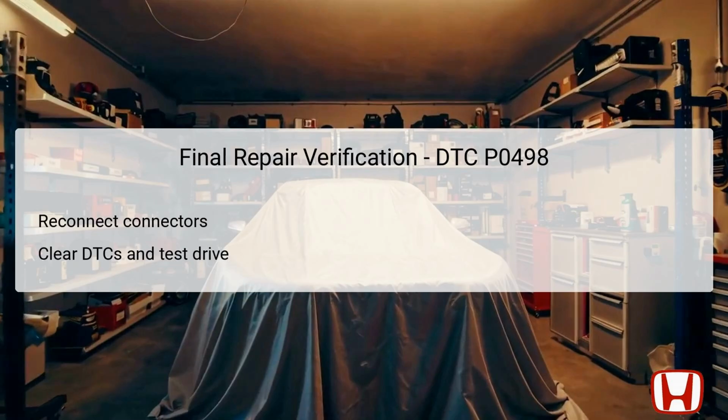The next step is to test drive the vehicle while monitoring the onboard diagnostic system for any recurring signs of DTC P0498. Successful elimination of the DTC without reappearance signifies that the issue has been effectively resolved. This step is essential not only for confirming repairs, but also for ensuring the reliability of the vehicle's EVAP system.